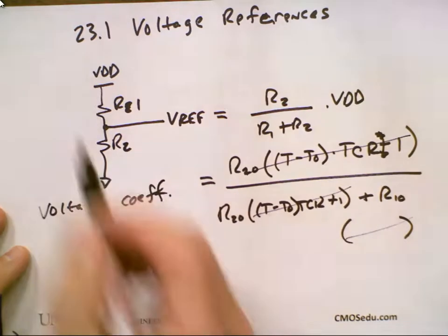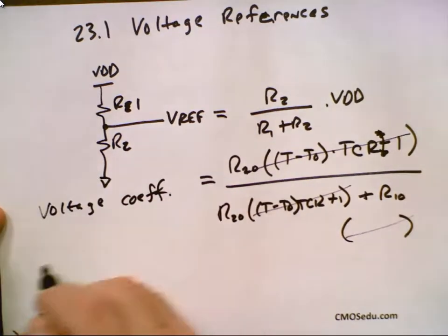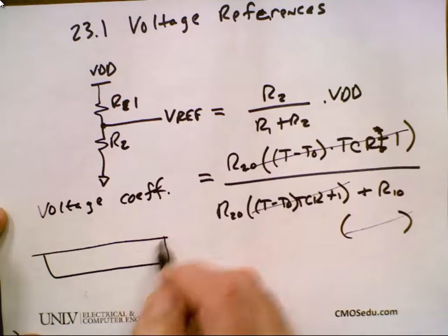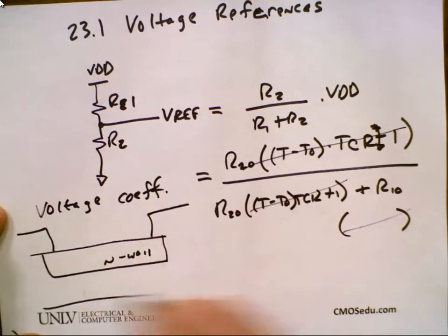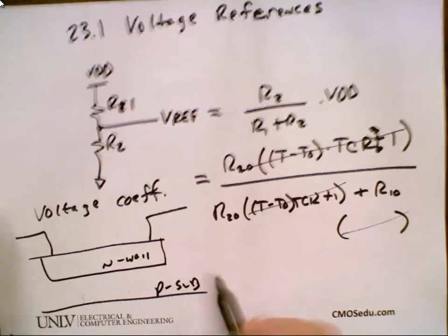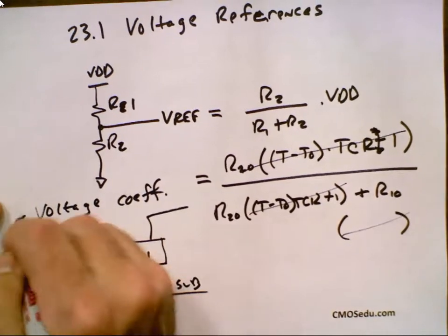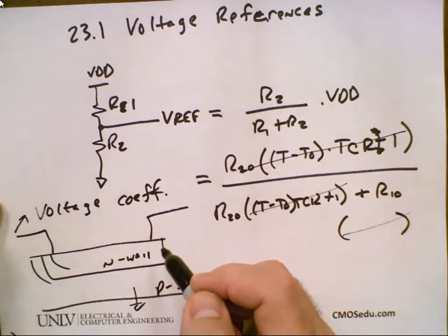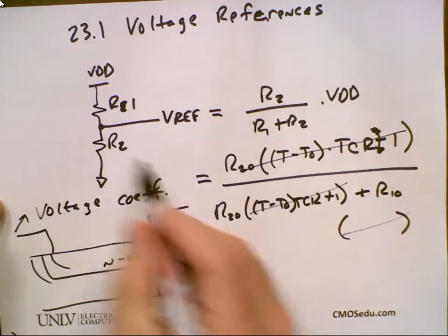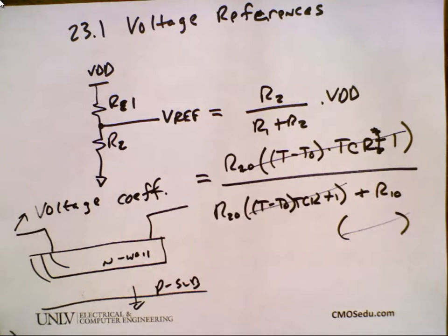So if you recall, if these are made with N-well, and you have your N-well sitting here, and each side is N-well's grounded. If you raise this potential up, the depletion region grows and your resistance changes, all right? So that forces you to use like poly resistors or whatever, so there's limitations there. Sensitivity to VDD is another issue.